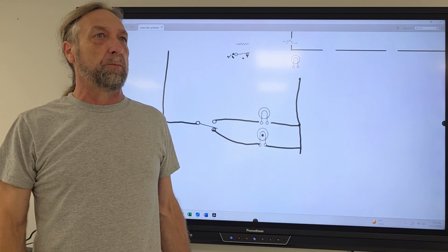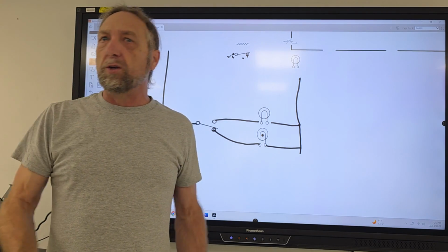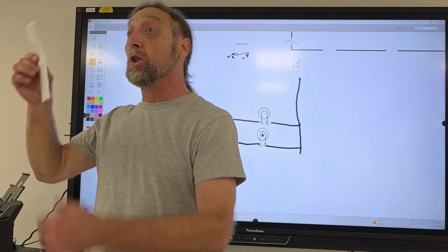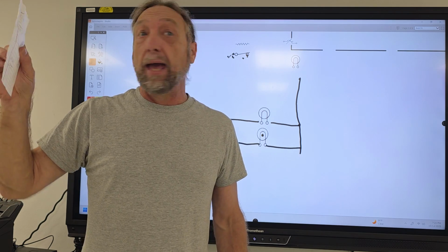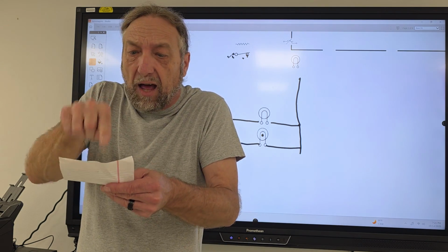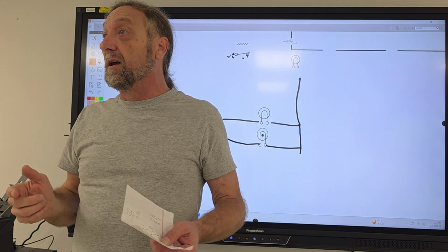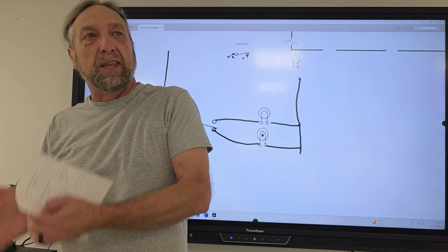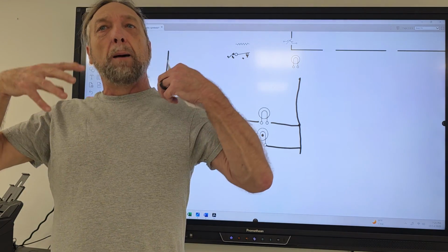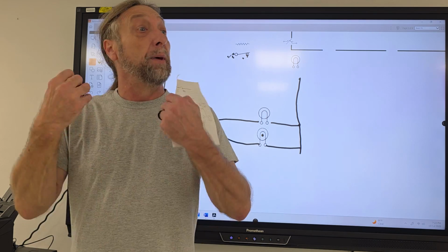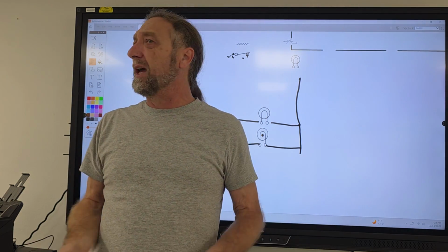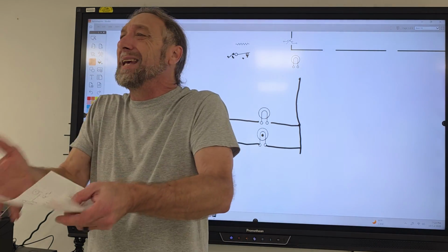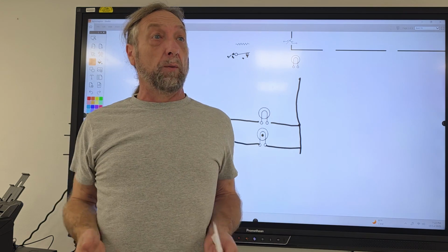Every time you touch a machine, I don't want you testing parts without looking at the diagram. Even if you're just looking at it, say, that's the part I'm testing. This is what's going to make you better at diagrams, looking at them every day. You can't just spend one day a week studying diagrams, or sit at the table drawing diagrams all day.